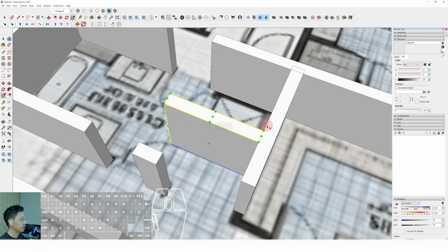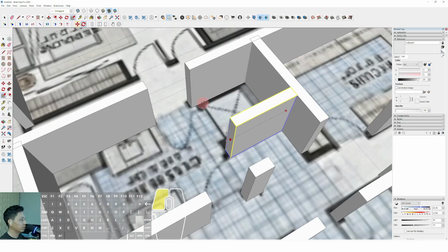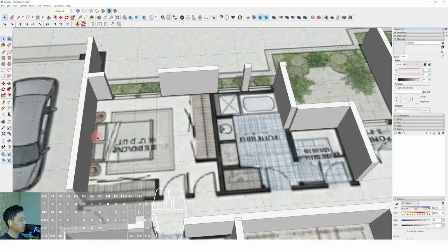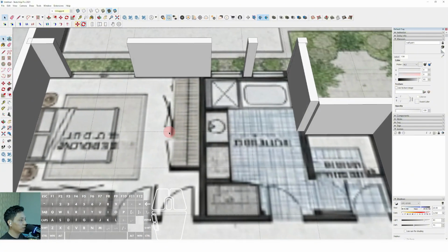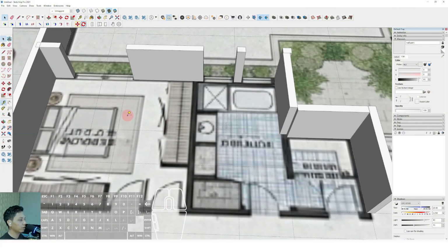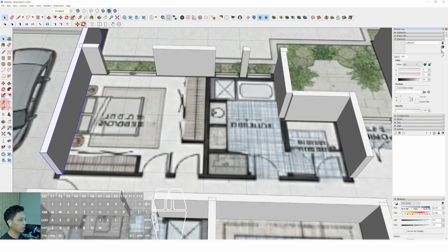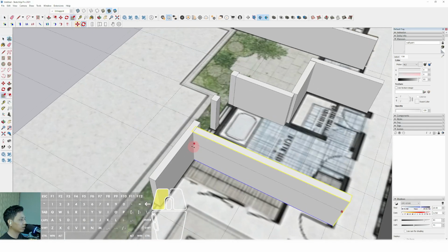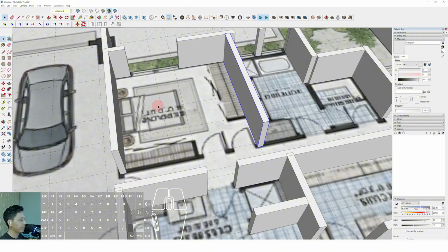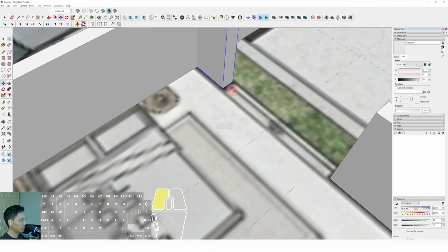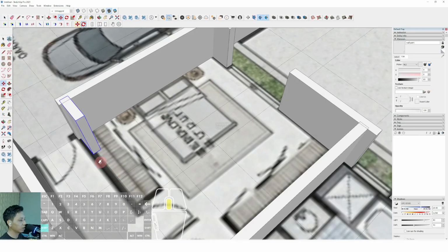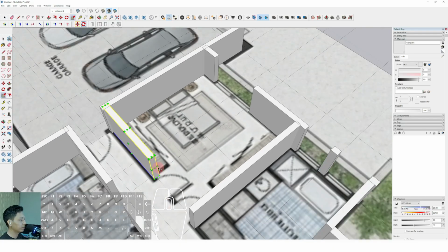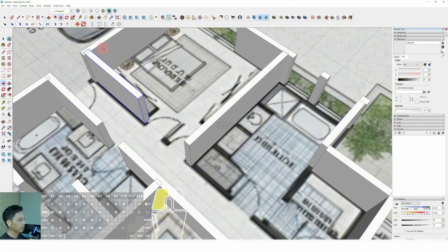Okay, there is a little wall in here, but for the next step we have to readjust for the floor plan. Okay, you can click from this guideline till this wall, around 1.6 meter. You can duplicate again the wall until this position, and just scale it again. Select move, tap control, and place this position in here, and again.